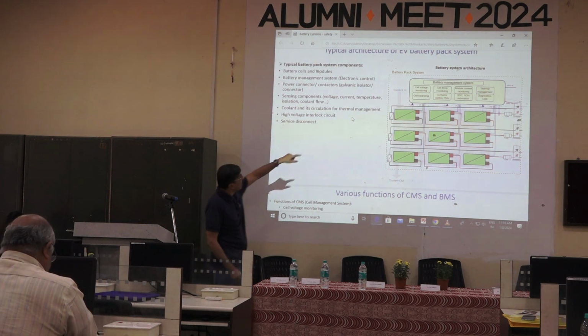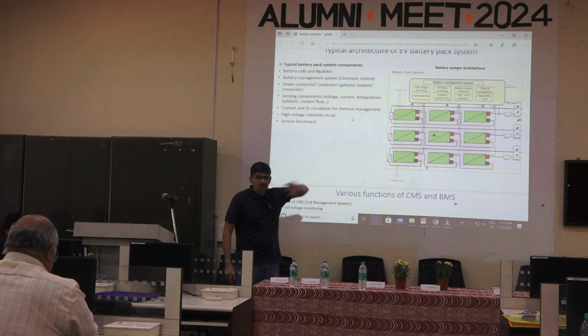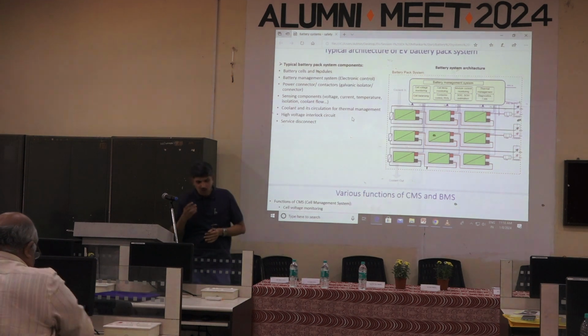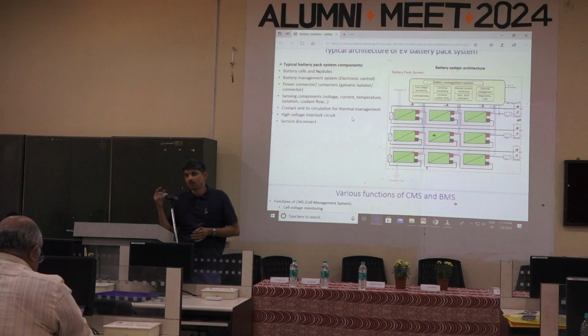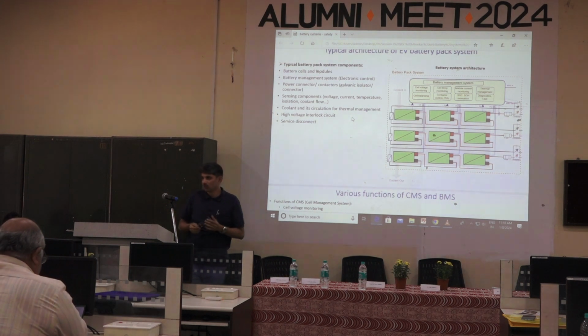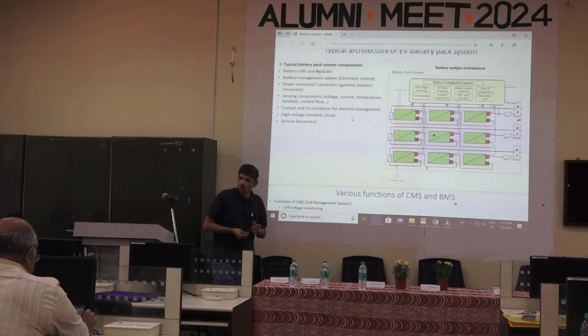Now if you see the kind of management systems working there, these are all connected through CAN. So if you want to learn more about CAN 2.0, you must have gone through that, or J1939 SAE. That is the best standard describing how the CAN protocol, SPN, PGN and all work there. So generally we connect batteries on CAN. Now PoE is also coming into the picture, or over Ethernet, and those protocols are also there.